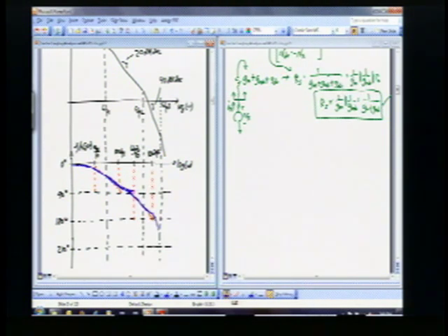For this next one, the phase is going to do something like that as we go through that next pole there. So that's what the phase response ends up looking like. And so what you're noticing is that phase changes quite a bit after you go through these poles. And we're going to get to this much later in the class, but we're going to be very concerned about what this amplitude plot looks like and what this phase plot looks like in relation to the amplitude plot, because that's going to affect stability.